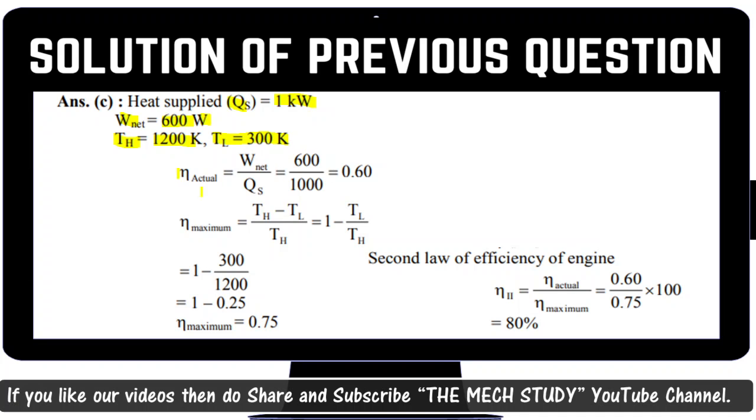And if you calculate the second law efficiency, if you observe over here, the second law efficiency consists of the actual efficiency divided by the maximum efficiency. Actual efficiency comes from the W and Q_S terms, and the maximum efficiency is calculated based on the theoretical temperatures. So here W and Q play the role of calculating the actual efficiency, and the maximum efficiency comes from the theoretical perspective in terms of temperature.